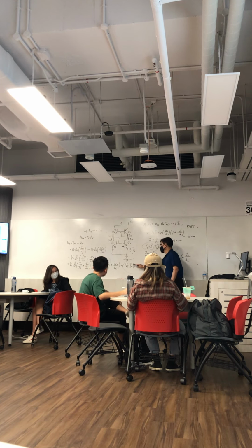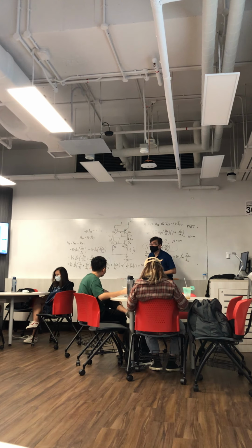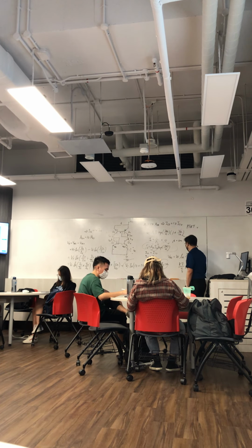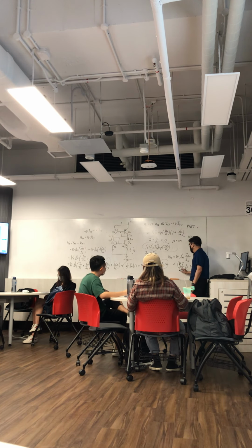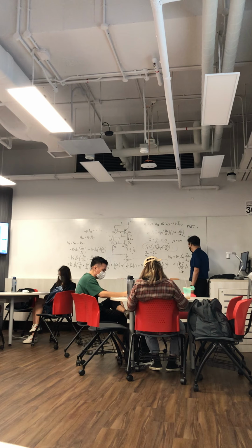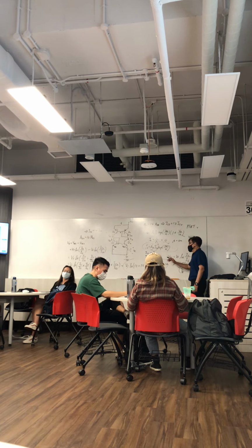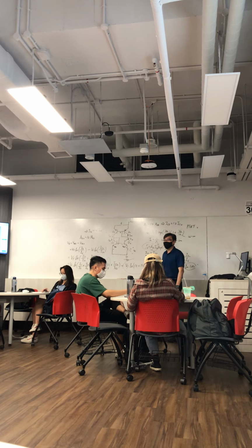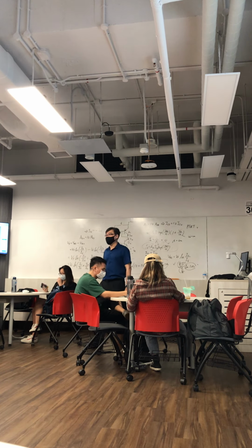If I want to get it correct, the PTAT voltage is equal to kT over q, then log 100. K is the Boltzmann constant, a fixed constant. Q is the electronic charge, also a fixed constant. This is also constant. And T is absolute temperature. So you can see this voltage is linearly proportional to the absolute temperature. So it's called proportional to absolute temperature.